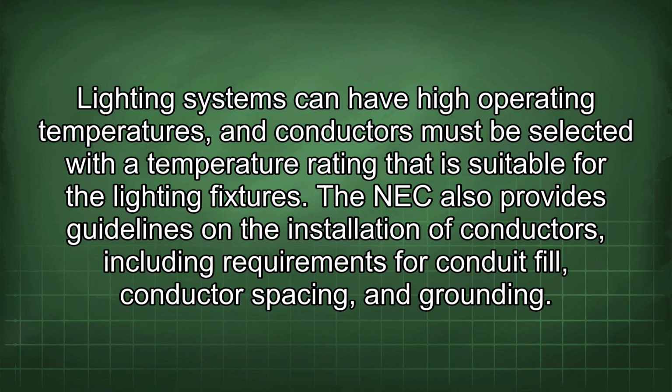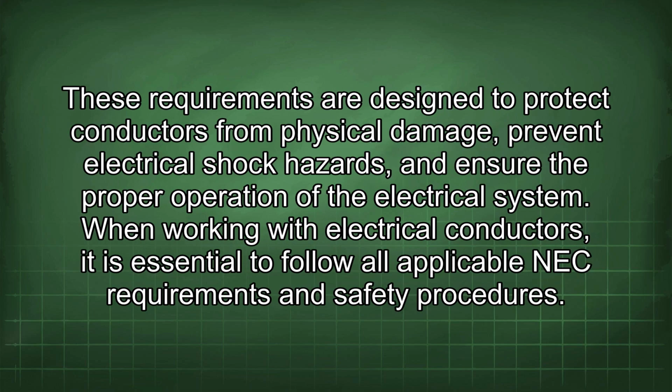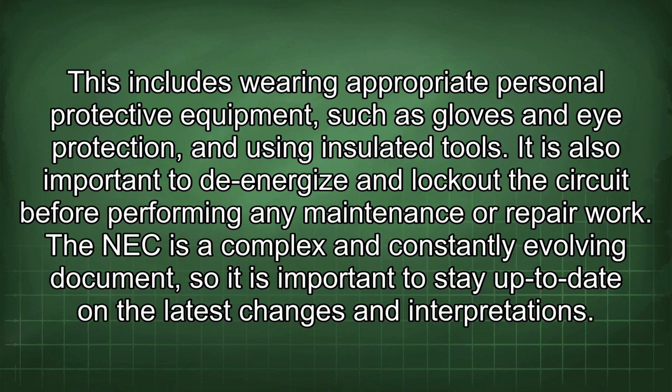the lighting fixtures. The NEC also provides guidelines on the installation of conductors, including requirements for conduit fill, conductor spacing, and grounding. These requirements are designed to protect conductors from physical damage, prevent electrical shock hazards, and ensure the proper operation of the electrical system. When working with electrical conductors, it is essential to follow all applicable NEC requirements and safety procedures. This includes wearing appropriate personal protective equipment, such as gloves and eye protection, and using insulated tools. It is also important to de-energize and lock out the circuit before performing any maintenance or repair work.